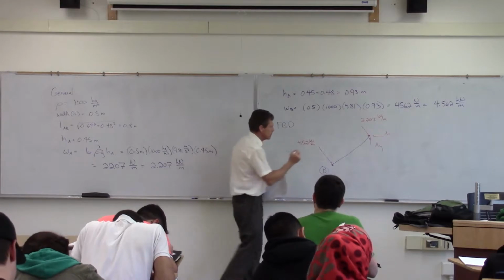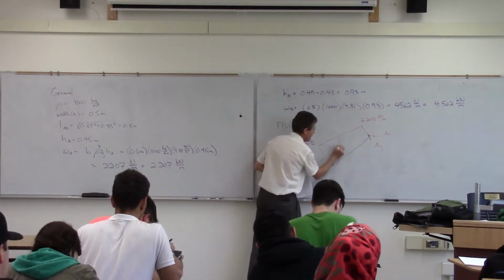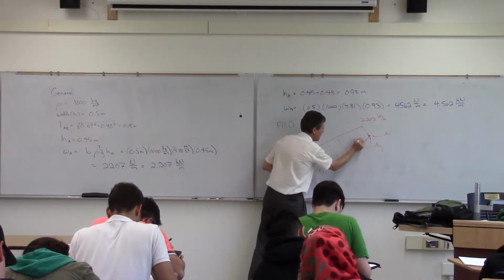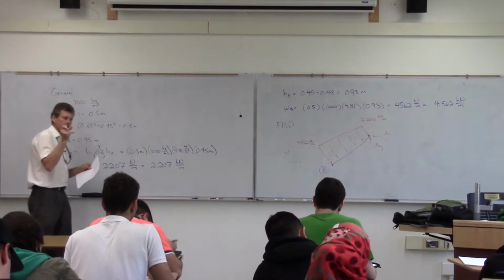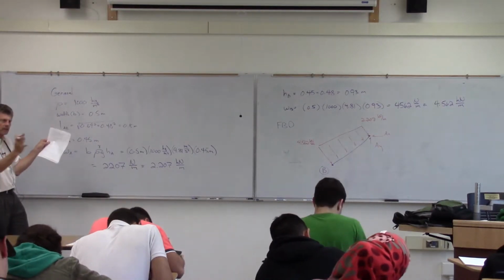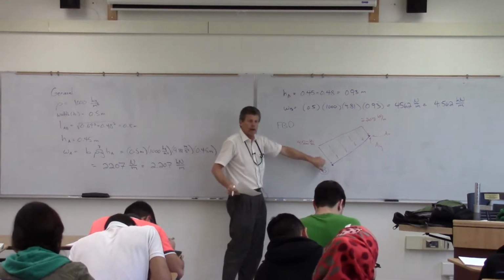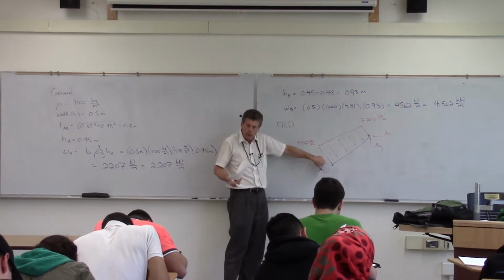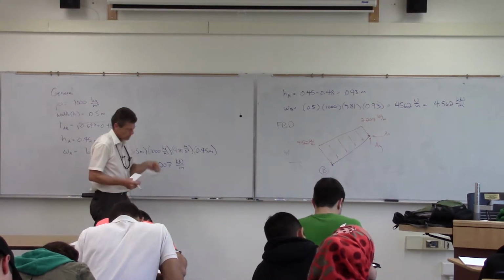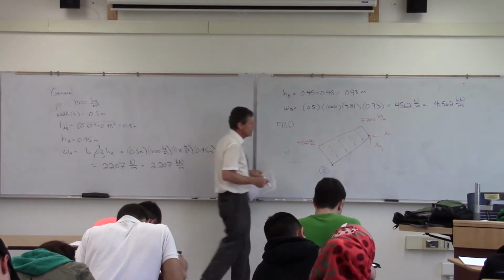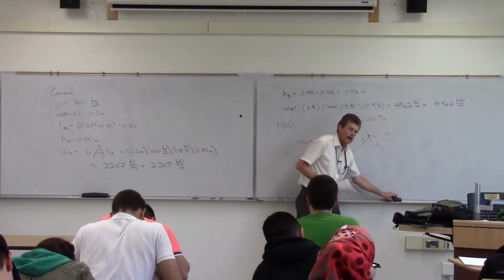And this is what our distributed load will look like. So what we've done is simply with that B, and that's why we want to take that B into account there, is we've basically taken that dimension out of there, and we've created what looks like a beam load, something we can deal with now in terms of our statical equations. Now, of course, distributed load, we don't know how to deal with that, basically.